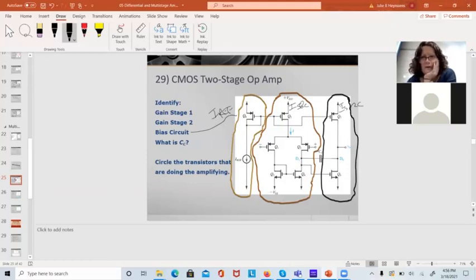When I want to decipher what's going on here, I try to draw a line between the input and the output. In this case, I'm going to start at the positive differential input, and I want to get to the output. So I'm going to have to go through my diff amp gain transistor and through this transistor right here. So Q1 and Q2 are a diff amp. This is easier to decipher than that big ugly op amp. This one right here, my signal input is coming in on the gate. The output is off the drain, so this is a common source.